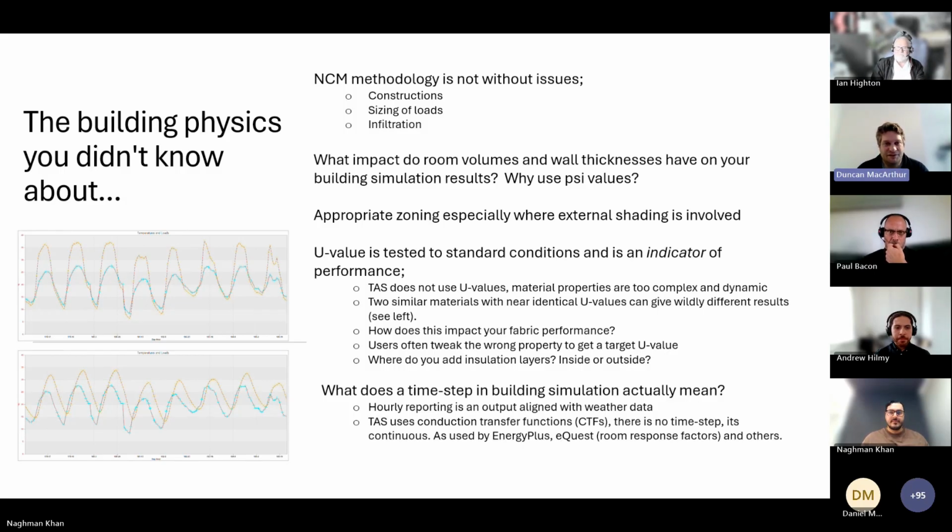And there's other things as well with the fixed level of infiltration. The number of hours that the system's operating is actually looked up based on the actual activity assigned to the space. So if you do simulate the same building with the setback temperature at a certain point during the day, you'll actually find that your number of hours operating in the system will be different to the one used in the calculation.